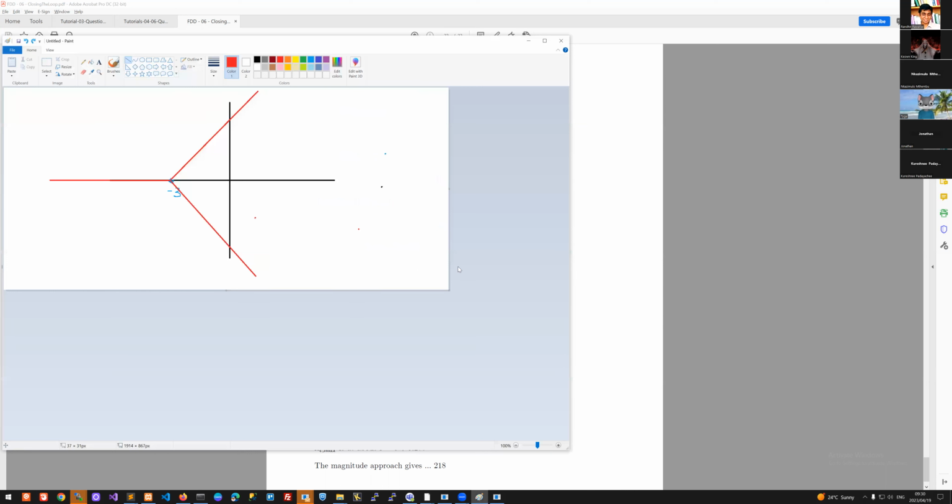So yes, we can do it numerically like we showed in the simulator, but we also have available this method for drawing our asymptotes. And you can see in this way, we can very quickly tell whether or not this is a stable process. So we can say, yes, there are regions where it can be unstable. And so it's important for us to figure out where these points are, what values of Kc will get us to here. Okay, any questions or comments there?